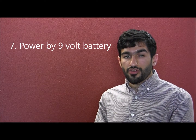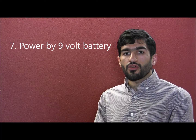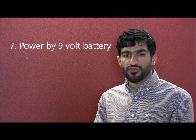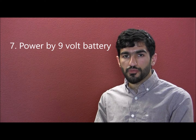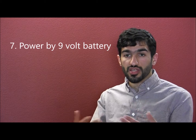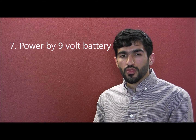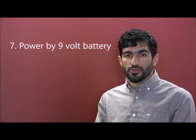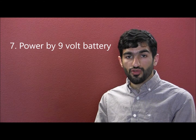The IoT smoke detector is powered by a 9-volt battery. The battery that we chose is a 9-volt 522 Energizer battery. The reason for choosing it was that it's widely available in the market. It provides the system with a range between 7 and 9 volts. It has a capacity of 500 milliamp hours.